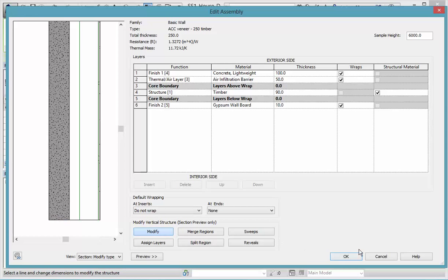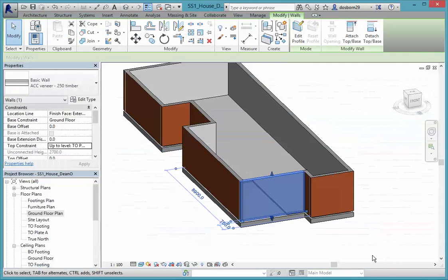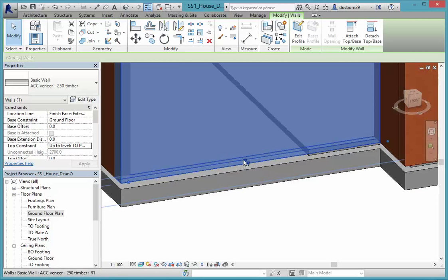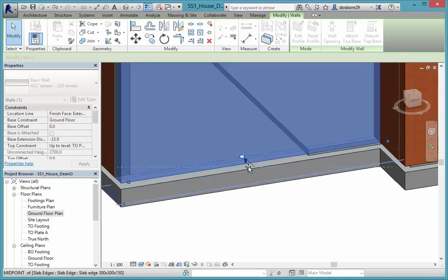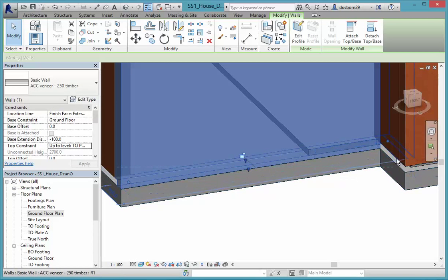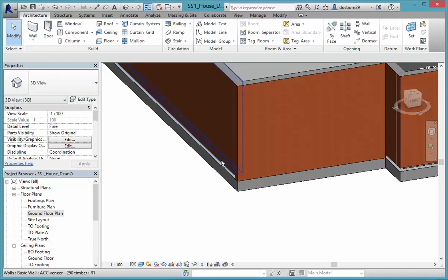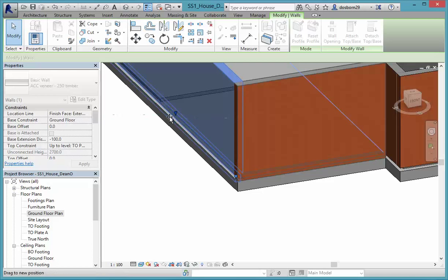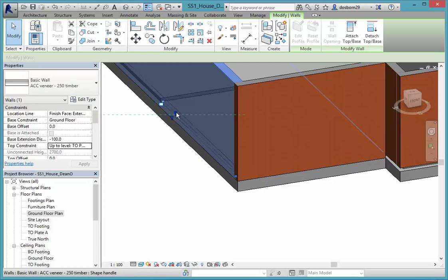Okay. Once they're unlocked, if we go back to our drawing, we just go OK and OK again. We come back to our drawing and we come in. You see you've got two little arrows there. One's for our outside and one's for our wall. So we just drag that one down till it touches the side, and we just work our way around on each of the walls, dragging that outside one down. We could drag both of them down actually, because that's just the air gap, that one there. We could drag that down, but I'm not going to worry about that one.